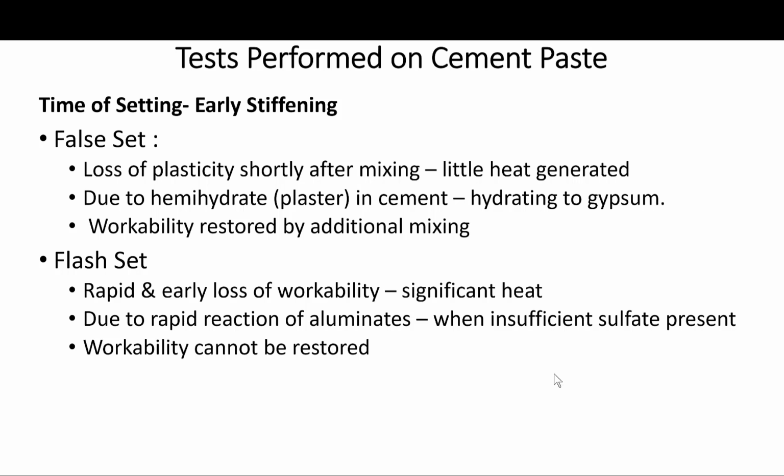The test for early stiffening is described in ASTM C451, using again the Vicat apparatus, where a paste is prepared with enough water so that the initial penetration 20 seconds after the completion of the mixing is about 32 plus or minus 4 millimeter. The final penetration is determined 5 minutes after the completion of mixing. The results are reported as final penetration to initial penetration multiplied by 100%.